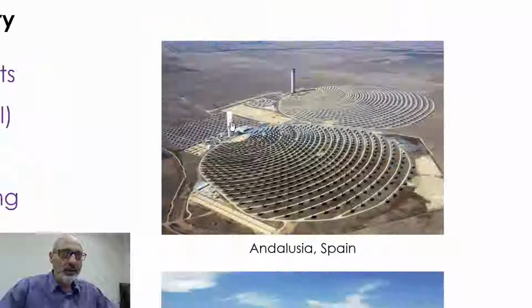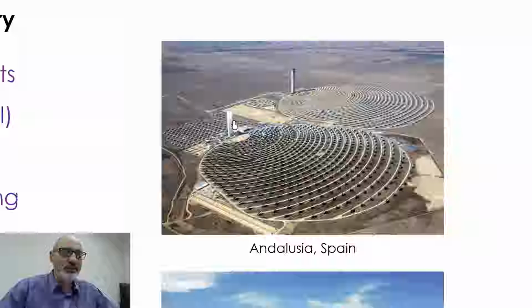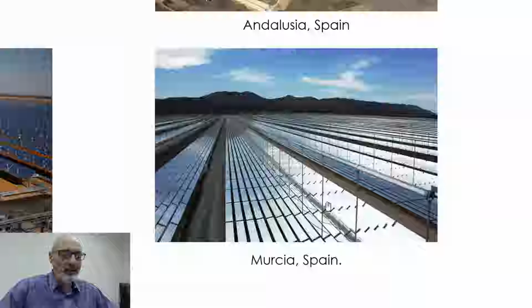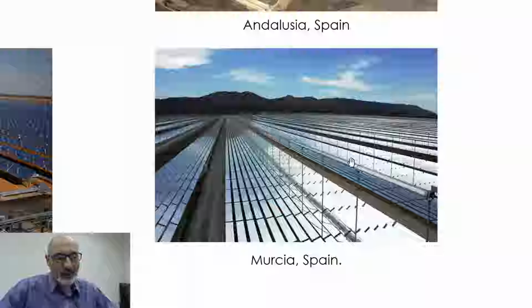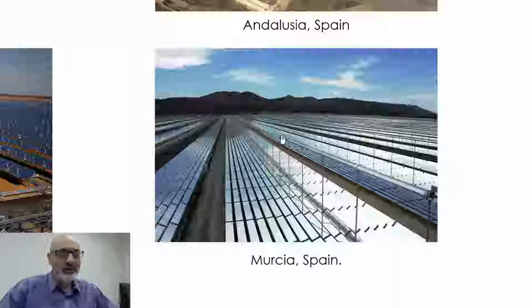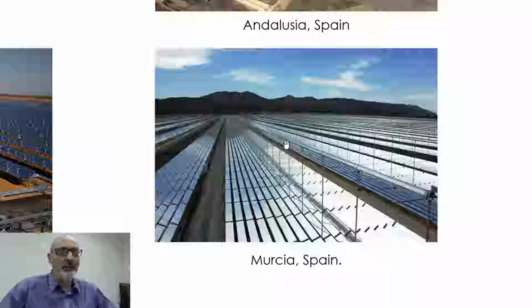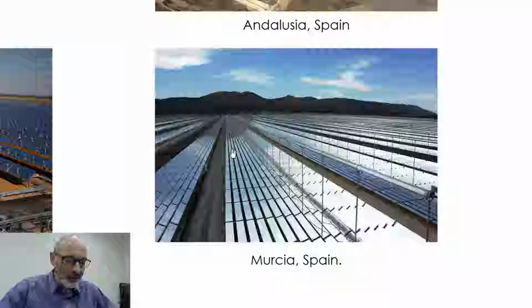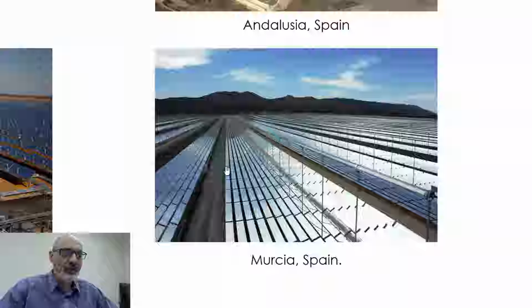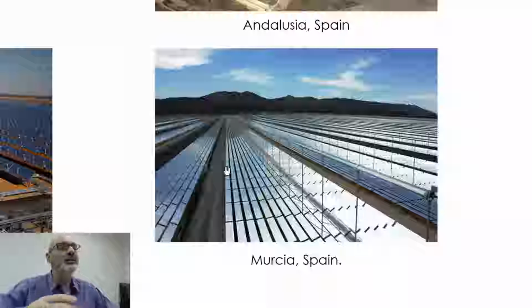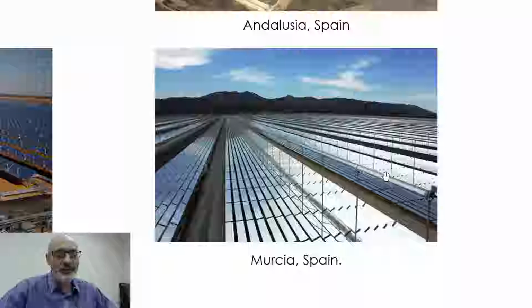So in the solar tower, all energy is concentrated on a point, and in this situation, the solar energy is concentrated on a line. In this line you have a tube. Inside of this tube you have the working fluid of the primary. We're going to see this. And the Fresnel system, those are flat mirrors, and they are able to move individually in order to focus the energy on this line.